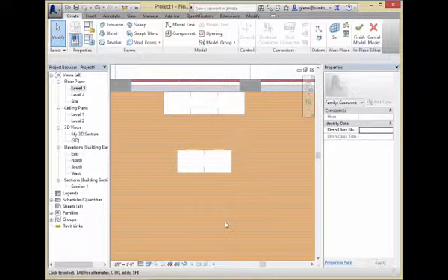Extrusion is the idea that we're going to draw some sort of profile on a plane, and we're just going to give it a third dimension by extruding it, pulling it perpendicular to the plane, a set thickness. So a lot of things are that. If you're going to model this lectern, this countertop right here, this is a rectangle that just got extruded to make it fat.